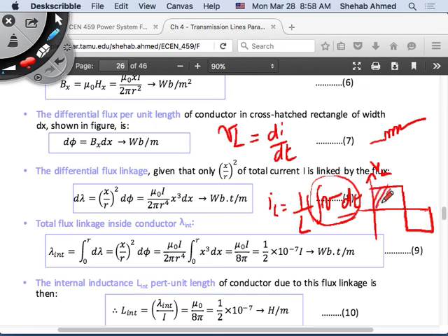When you place voltage across an inductor, what happens? Flux builds up around the inductor. If you place a voltage, current will flow through the inductor coils, and then flux will build up around the inductor. This flux is linking the inductor turns, and it's called flux linkage. How do you calculate this flux linkage? It is this integral of voltage.